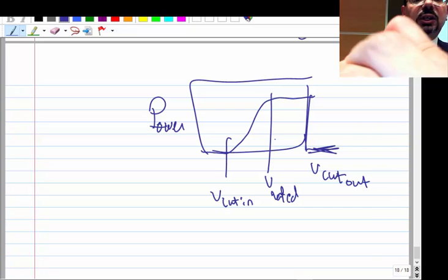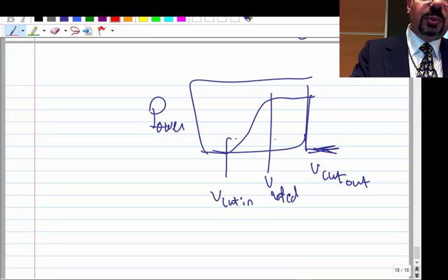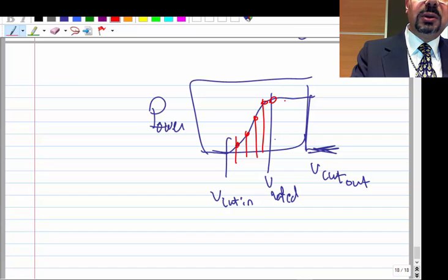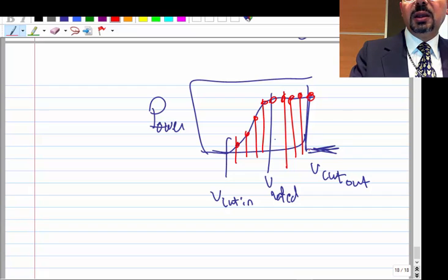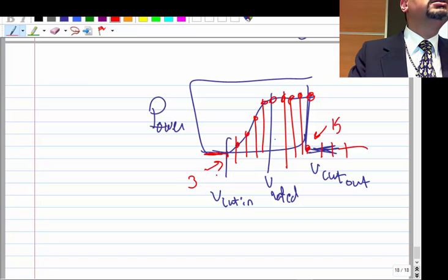Okay. So what you need to do on this graph is to basically read those numbers to the best of your eye can do. You will get those numbers. Once the velocity hit, let's call this 15 and let's call this 3. If the velocity is 15 or higher, you get 0 power. If the velocity is 3 or lower, you get 0 power. If the velocity is 4 or 5 or 6, you get how much? You get this number that you are reading from here.